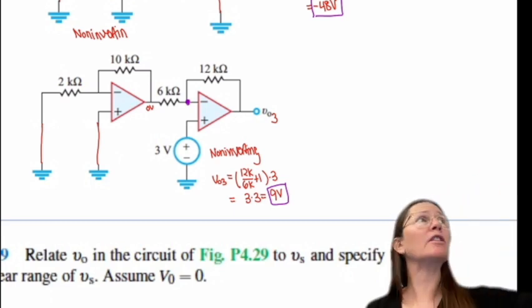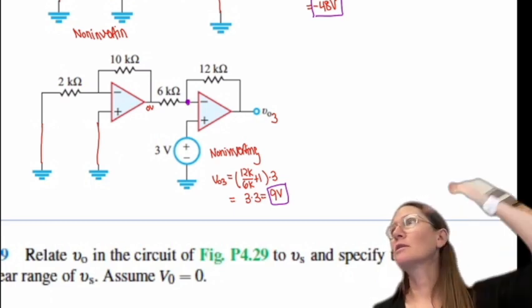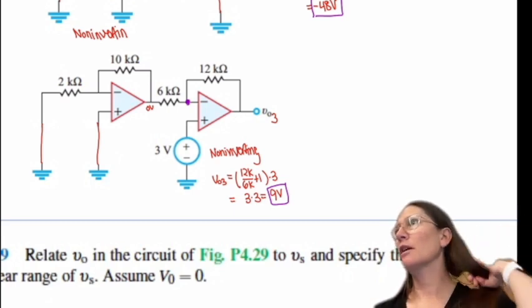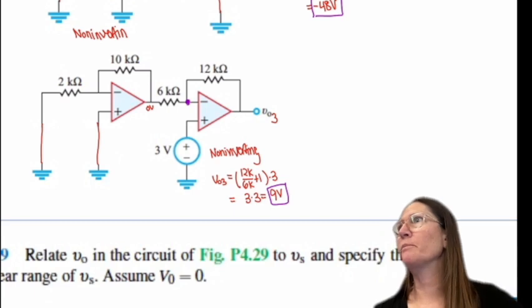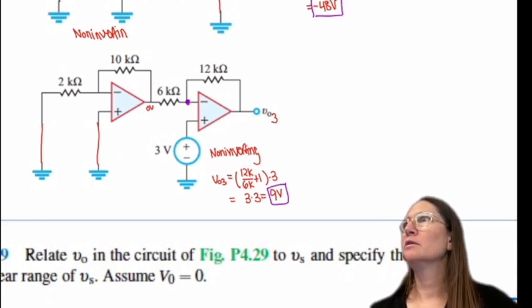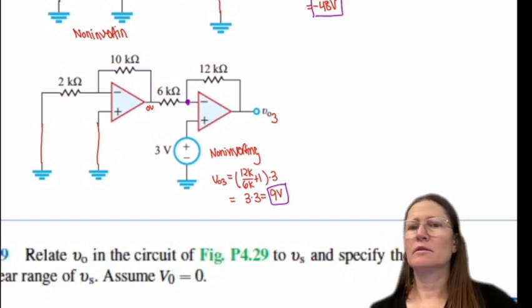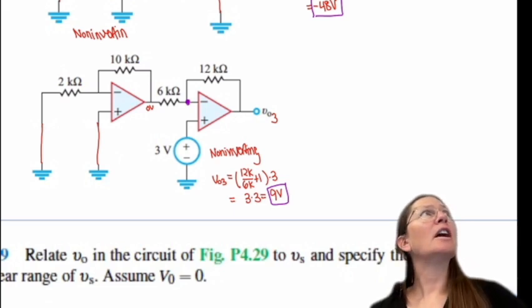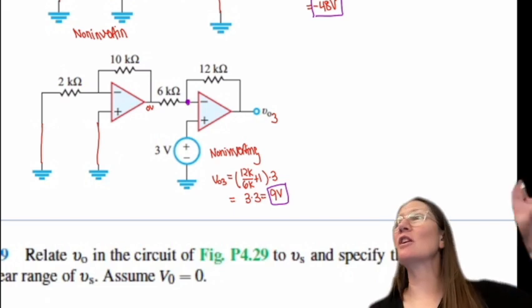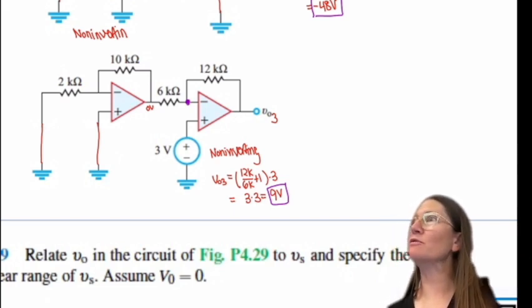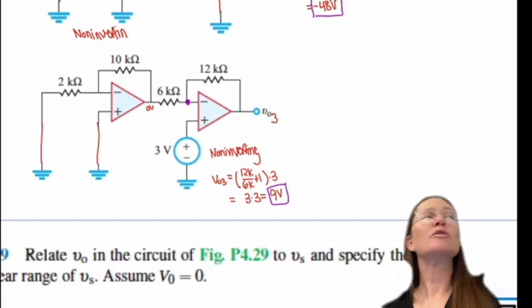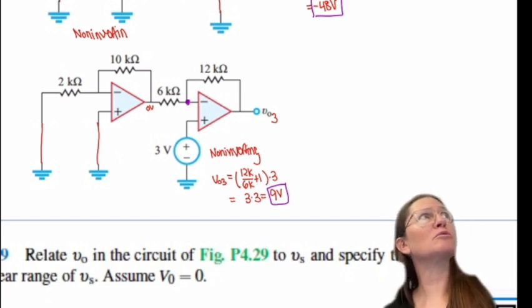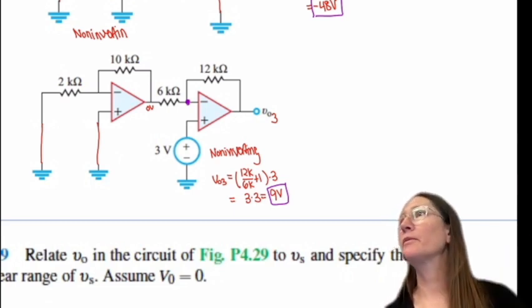So you're looking at that 3 volts as the input in there. Yes, it's a plus on that bottom side. It looks a little different because you have an op amp there, but it really is still 0 volts, or ground. So you don't amplify that side, but the 3 volts still has to get amplified.